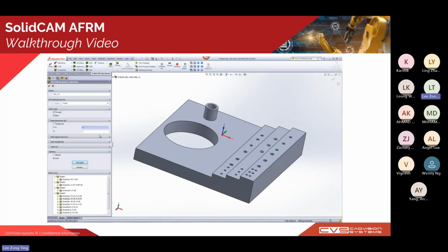And for the hole recognition as well, you can see in these solid models, there are different types of holes: small holes, big holes, chamfer holes, or drill holes. So you can see here, there's also a similar filter like pocket recognition. We can filter out those big holes that we don't want, because we don't want to use a drilling operation to do a big hole, right? So we can filter them out. After we filter out, we can press one button to find all the holes within these solid models.